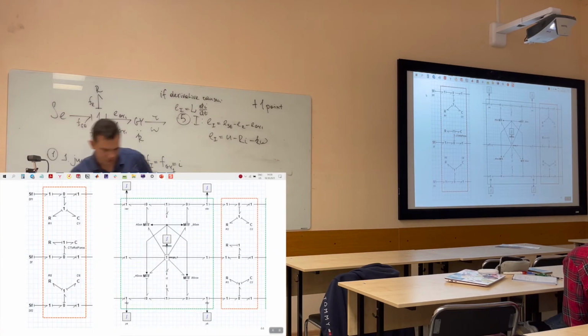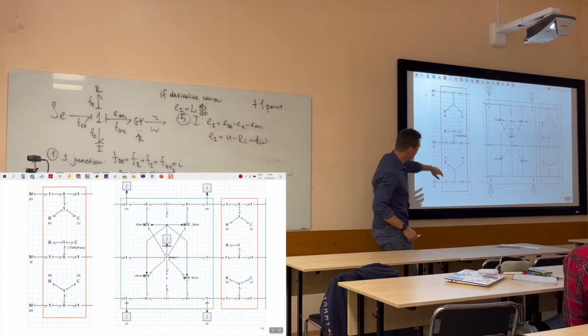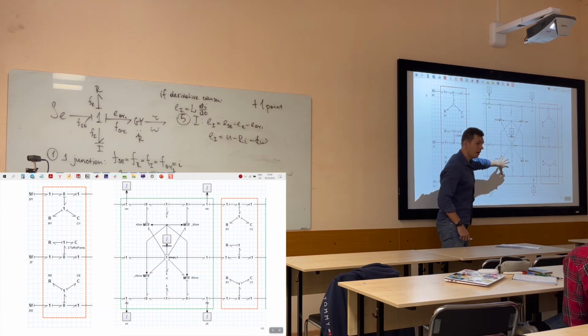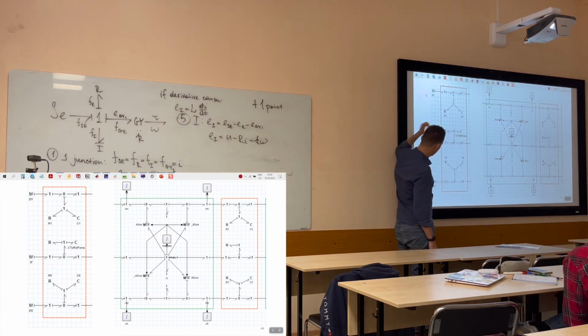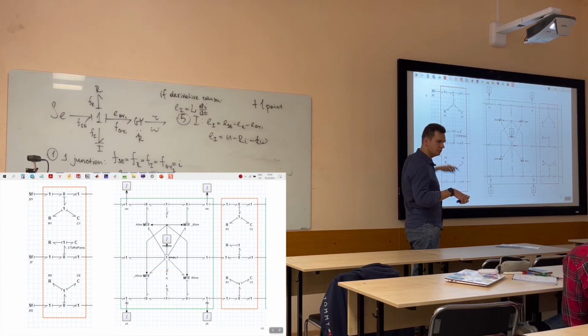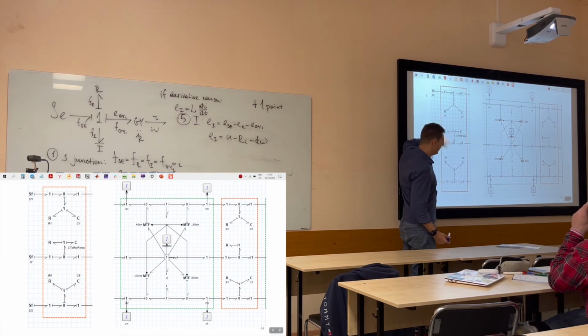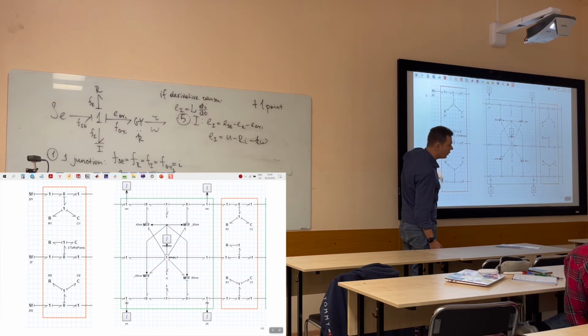It's like a joint, and this in green is a body. This source of flow is a source of angular velocity for a link, and those sources of flow are like the x and y linear velocities for your frame that must be equal to 0, such that the linear component equals 0 and there is only rotational motion.